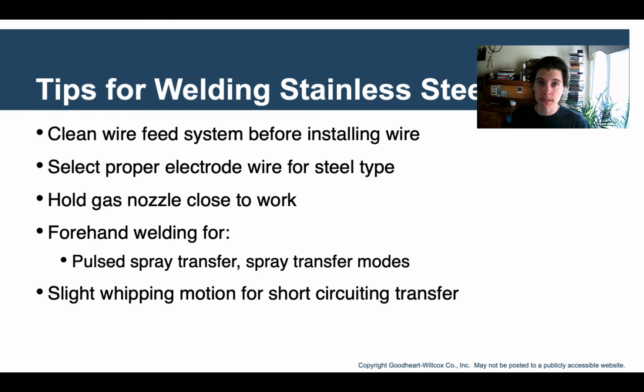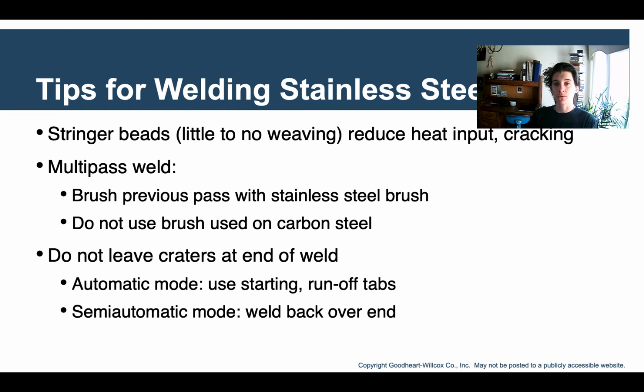Unfortunately, we don't have any stainless steel electrodes at OCC, so I can't really set anything up for you to test out, but this is all hopefully helpful to you later on if you do come into contact with some stainless. Use stringer beads, little or no weaving. Again, that reduces the heat input.